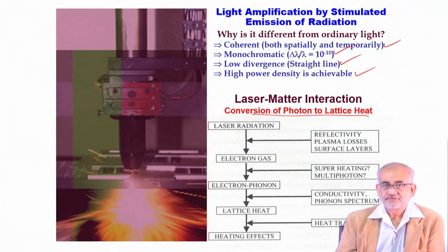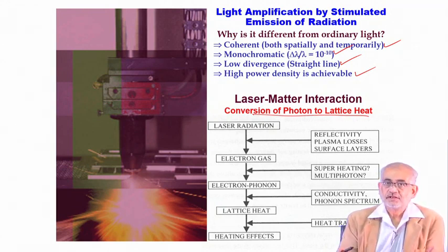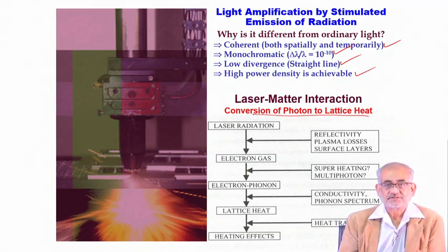Now, one way of overcoming this problem would be either you raise the temperature, where the coupling efficiency increases, or you go for lower wavelength lasers, so that the coupling efficiency increases. And for that reason, you would prefer Nd-YAG laser or solid state laser, or for even shorter wavelength one goes to excimer lasers or diode lasers and so on and so forth.